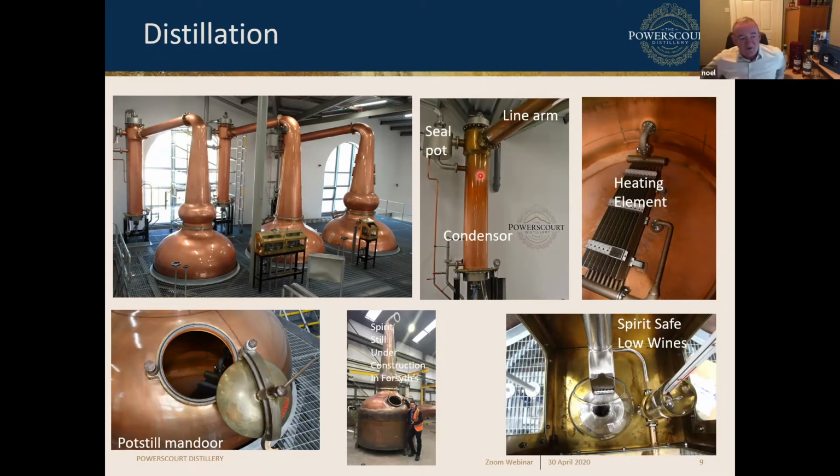Also on that photograph, you can see what we call a seal pot. This is a safety device. In a distillation system like this, you have to be careful when you're finished distilling if you either draw out the liquid too quick, or if there could be a sudden drop in temperature and the vapor condenses very quickly, then the actual still could collapse in, because a vacuum is created in the still.